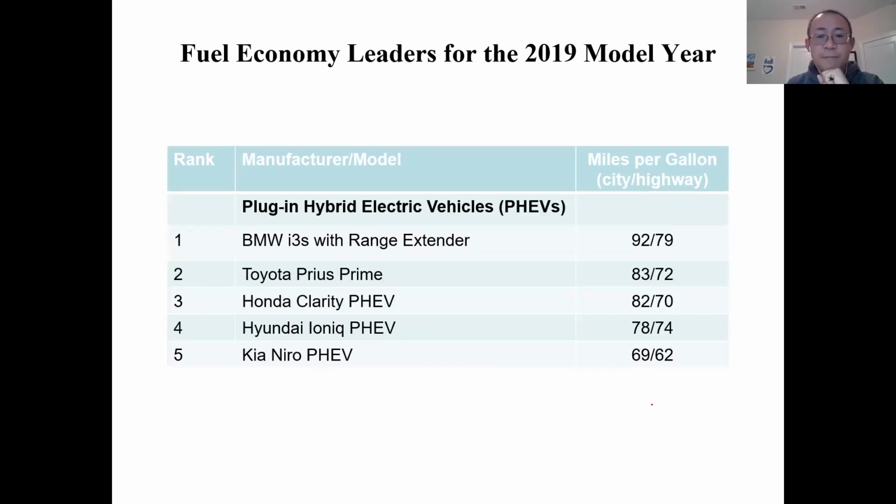Another type of EV is called a plug-in HEV. The difference is that it is still a combination of battery and gasoline technology, but the batteries in these PHEVs can be charged as well. Basically, after you get home, you plug in the car and charge the battery.